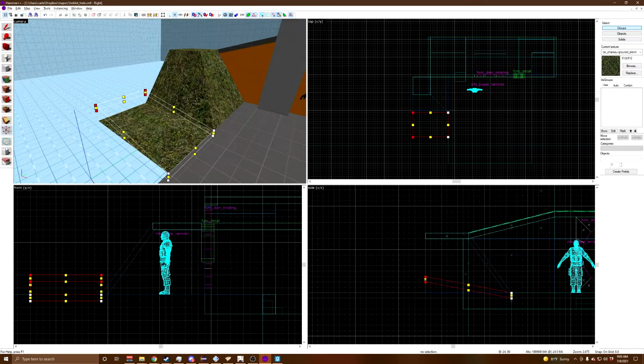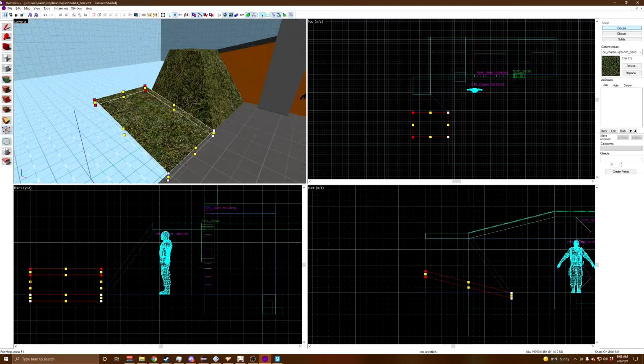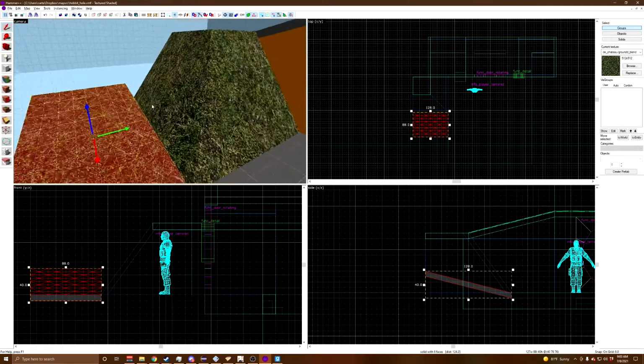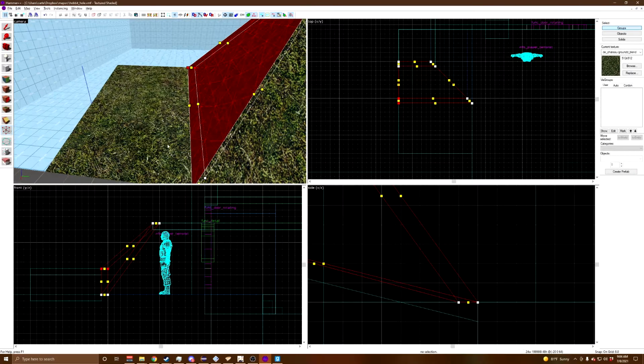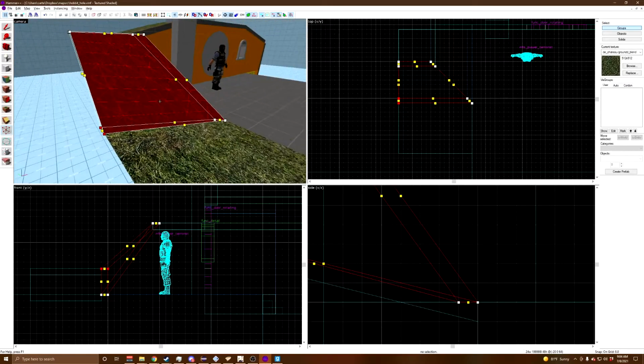So I'm going to create a new brush, raise it up with the vertex tool until I find a slope that I like. Now to make sure that everything sews, I'm going to take its adjacent displacement and raise the bottom left vertexes up to meet it at the top of the slope. As you can see from the red highlight, this resulted in an invalid solid. The reason being because this vertex here doesn't follow the slope.